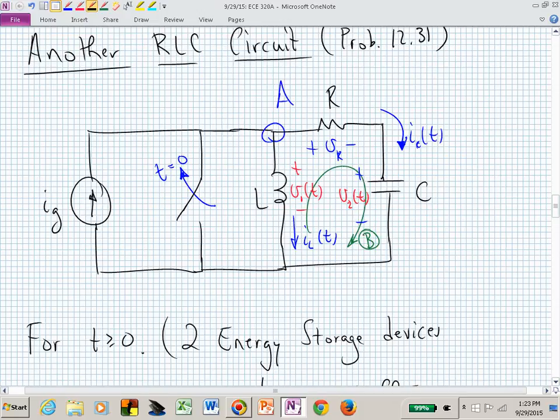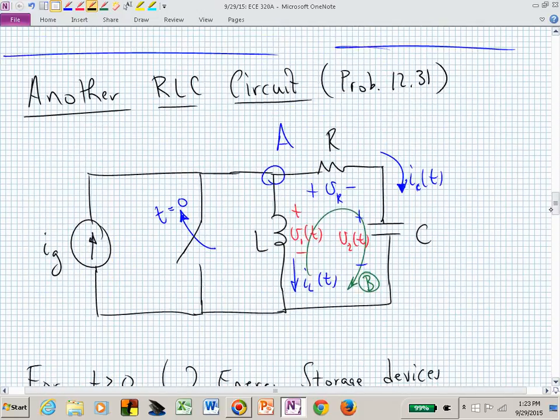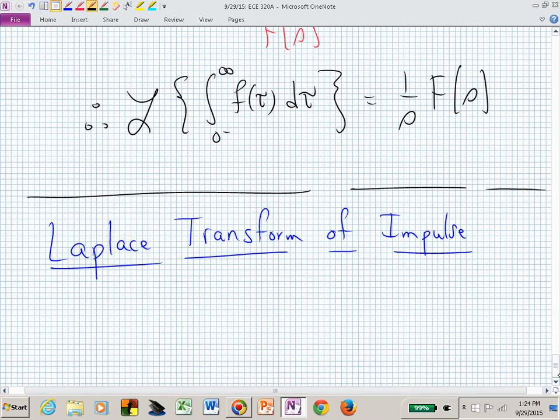What that's going to do is establish some current instantaneously flowing in the inductor, and it will put some kind of charge on that capacitor. And now it's like you somehow initialized that circuit to some conditions, and you want to see how it responds to those conditions. That would be the impulse response. You could watch the capacitor's voltage or the inductor current and say, oh, here's the impulse response due to an impulse at that source and the current flowing through that inductor. It's basically what's going to happen when you energize those energy storage elements.